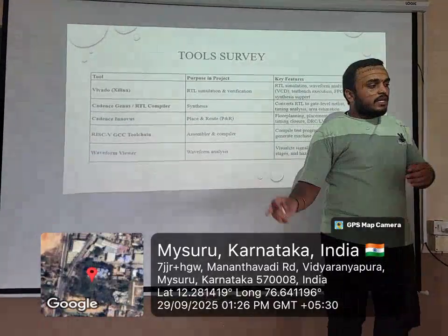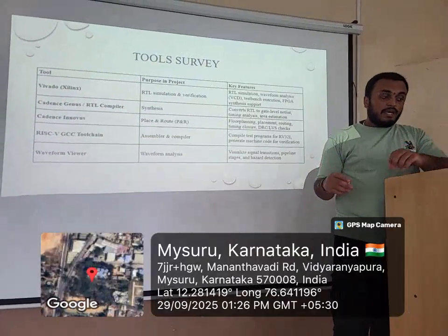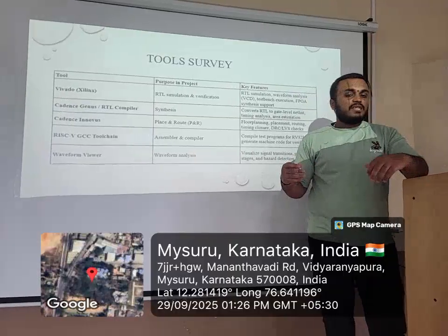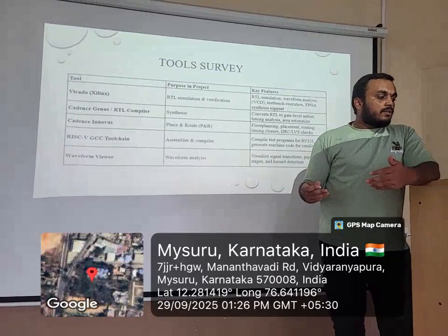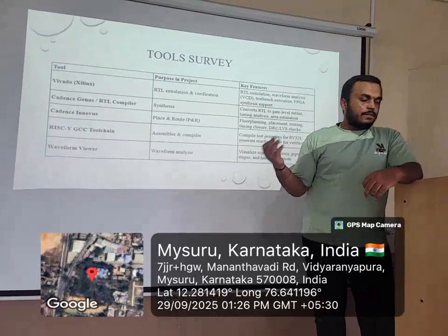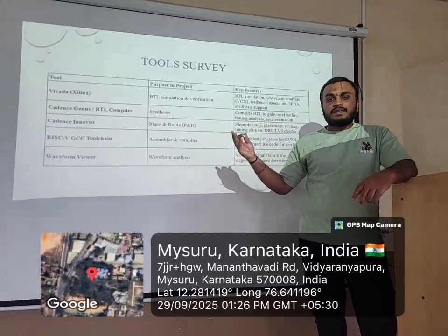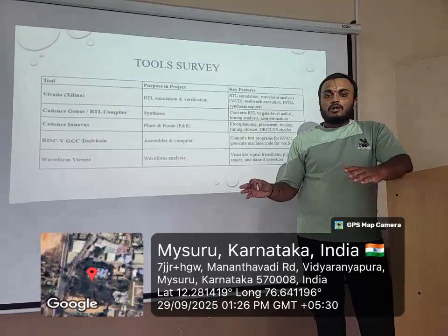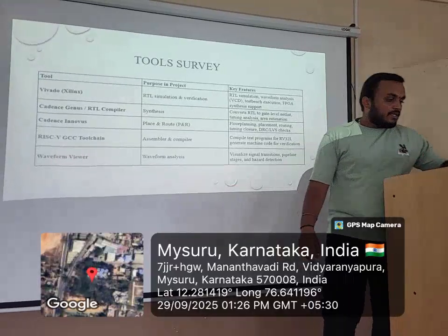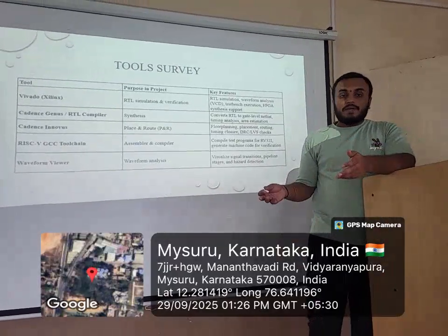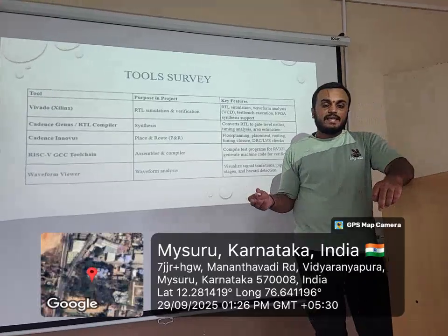DRC, design rule check, ensures the physical layout of the chip follows the manufacturing rules. It means that the physical layout we are designing follows the manufacturing rules given by the semiconductor foundry or company. We check whether we are matching those rules or not. The design rule check examines things like the minimum width of metal wires, minimum spacing between two wires, wire contact size, etc.